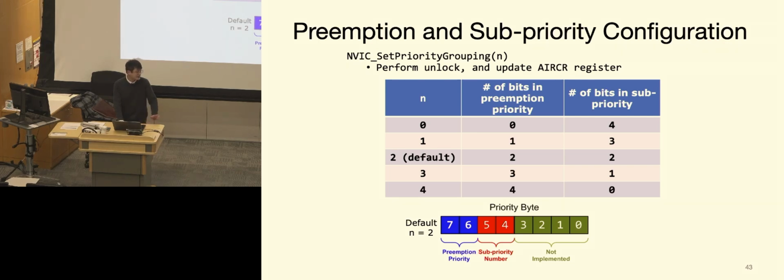The reason we use the top 4 bits here is a historical one. At the beginning, the Cortex M0, M1, etc. chose the top 2 bits, and then M3, I believe, the top 3 bits or something. And then M4, M7 became the top 4 bits. They just keep using the top bits so that programs you wrote for the later, more current architecture can still easily go back to the previous ones. Otherwise, you might cause some compatibility issues.